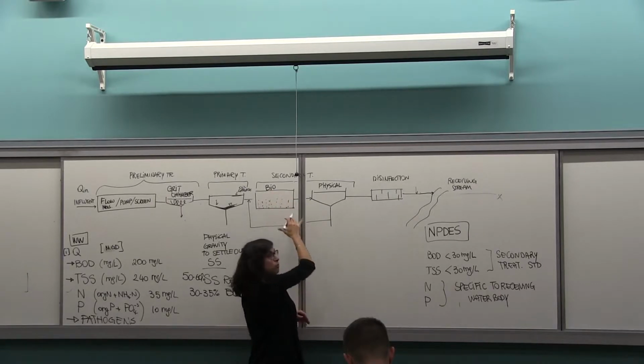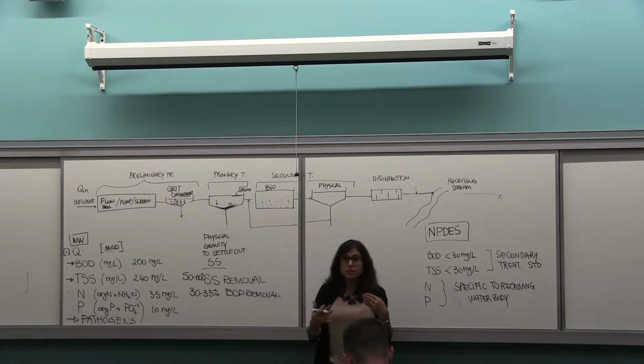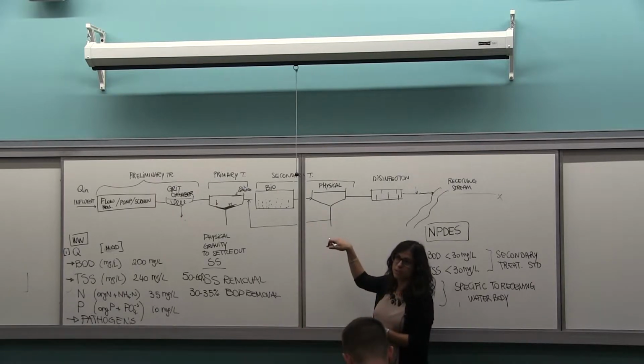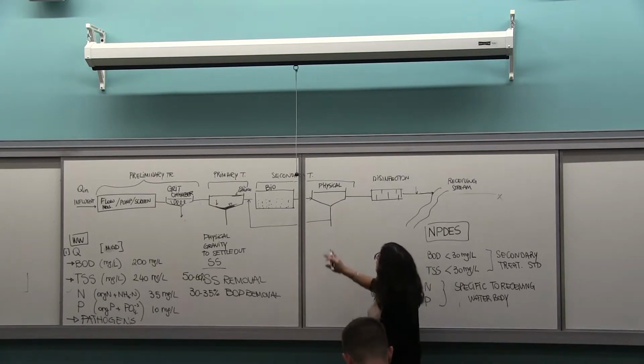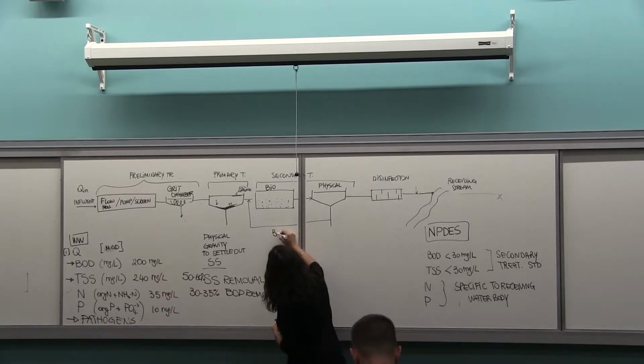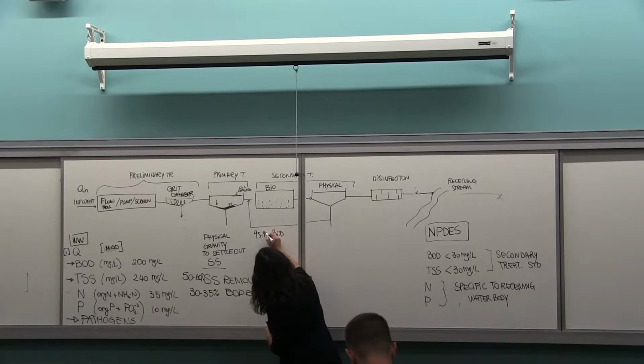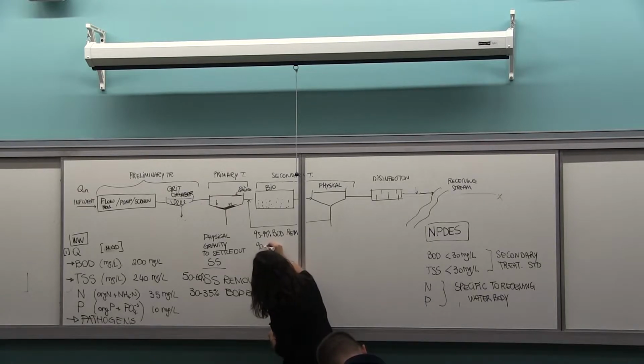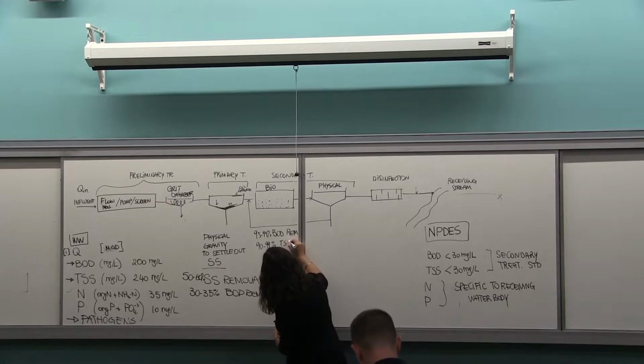So the soluble compound becomes particulate, so solids, and then you physically separate the solids. So this achieves 95 to 99% BOD removal, and 99% total TSS removal.